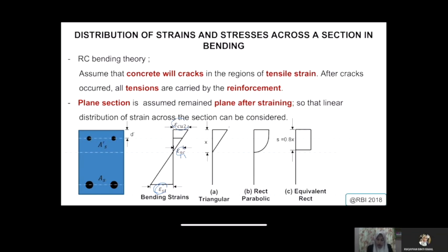And generally, this is how our triangular stress block will look for stress, and so on. But to make an accurate definition of the stress block for reinforced concrete, to represent the compressive part, we consider it parabolic, because that is how concrete behaves. Since it's not easy to consider a parabolic shape in stress block calculation, that's why we come up with the rectangular one.